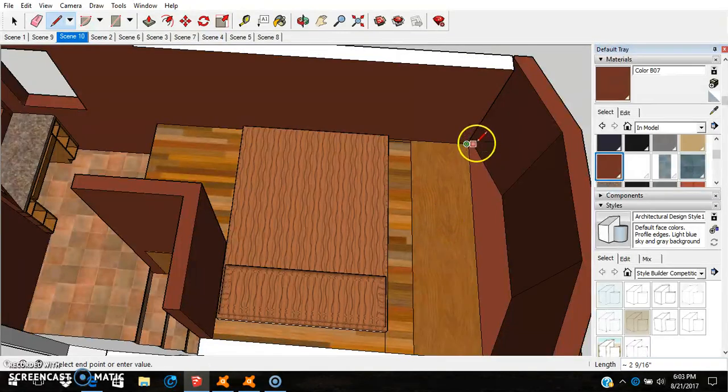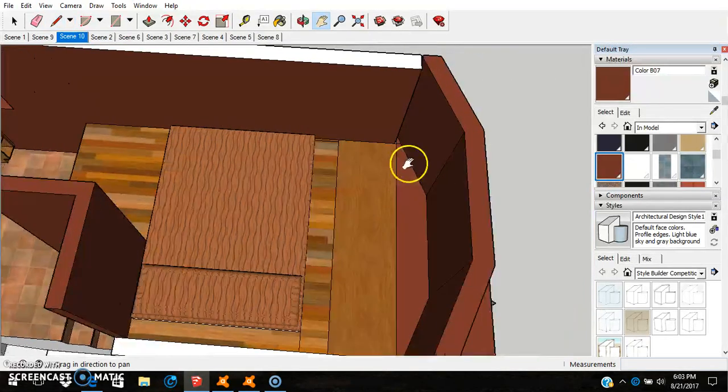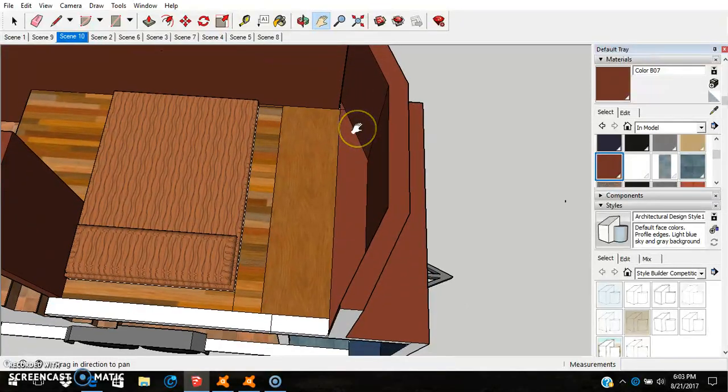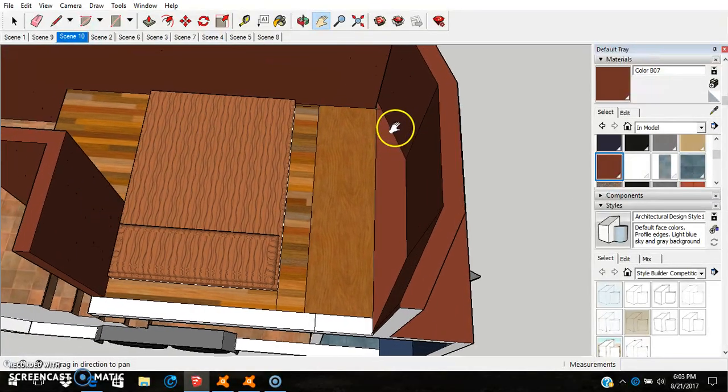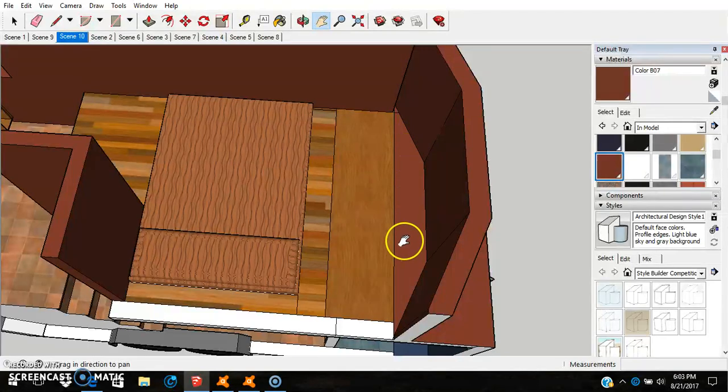And again, you can't trust lines, so you either use a rectangle, or we can go over here. We need an edge on this other side, so maybe we can figure something out. We'll just go ahead, do the rectangle, erase that. We'll come over here, click on that, click on this point, and then just go forward, and there, that should solve that. Erase this line here, and then all we need to do is go with a rectangle,